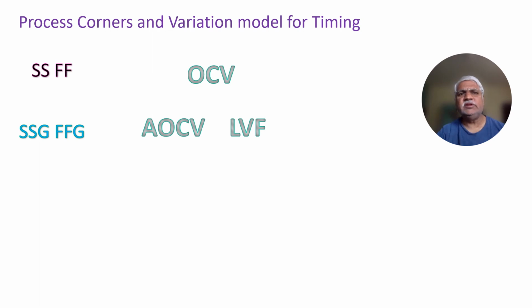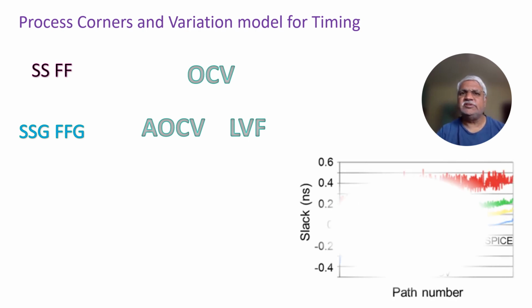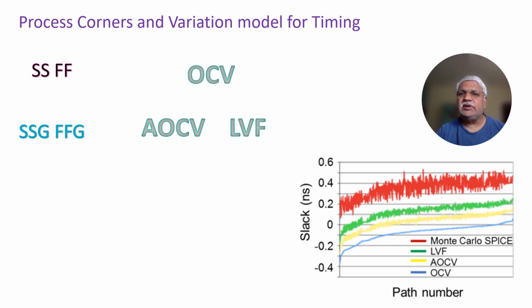These AOCV and LVF are advanced models compared to OCV, and in terms of accuracy, you will observe that for LVF, for different path numbers, this is the delay of different paths, and it is very closely converging with respect to the Monte Carlo simulation, which is very good. That means there is less pessimism in LVF.